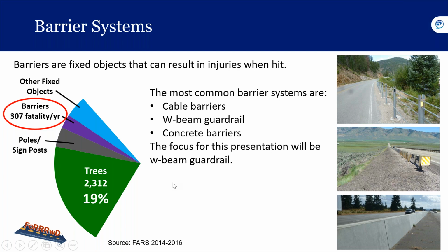Barriers are often a last resort, and we'll look at the different parts of barriers, requirements for use and testing, and common problems with installations or in-service barriers and maintenance concerns. If objects or harmful effects cannot otherwise be mitigated by removal, relocating, replacing, or made crash worthy, then a barrier may be the last resort. Barriers will sometimes increase crashes, but the increase is usually the minor variety or incidental contacts.